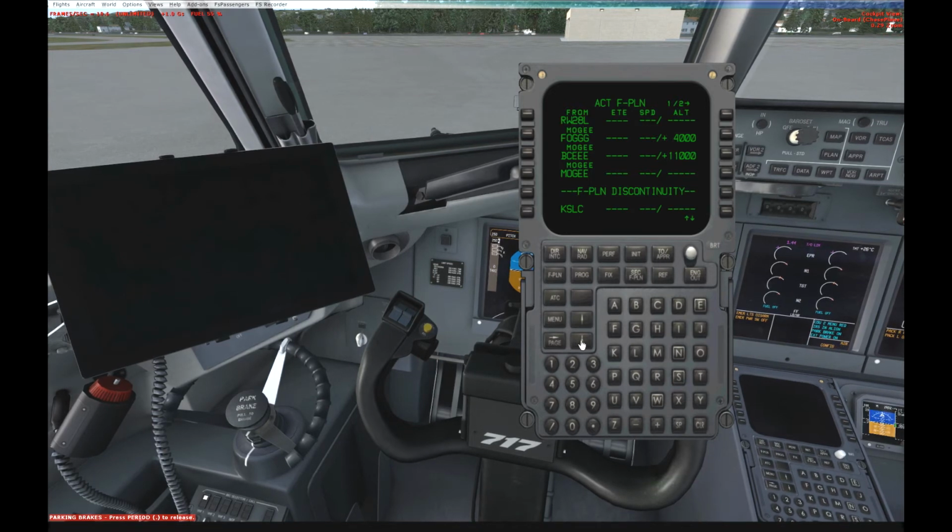Scroll here. What you want to do is get the last waypoint on your plan. Okay, taking off here. Here are the waypoints for the Fog 2 SID, and that's taking us to the Moji waypoint. That's the last waypoint in Fog 2. So what you want to do is click here to pick up the flight plan and continue entering waypoints. Or if the two cities were close together and you're going to go straight from the SID to the STAR, you click on here to select your STAR. But in this case, we're going to enter more waypoints.